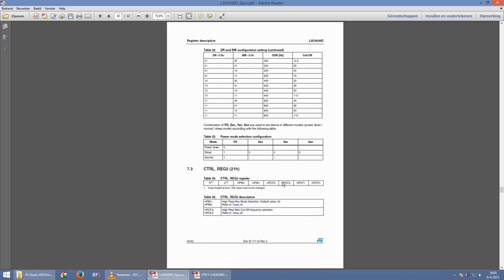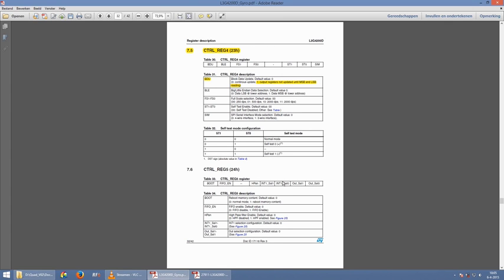The only thing that we need to change in control register 4 is the BDU bit. Because the angular rate data is transferred by 2 bytes, we need to be sure that the 2 bytes are from the same sample time. By setting the BDU bit, the output register X, Y or Z is not updated while reading the data. After a complete read of both bytes, the register will continuously be updated and always contain the most recent angular rate data.